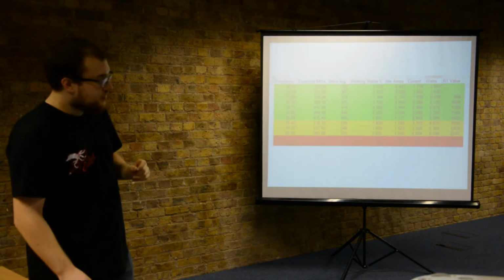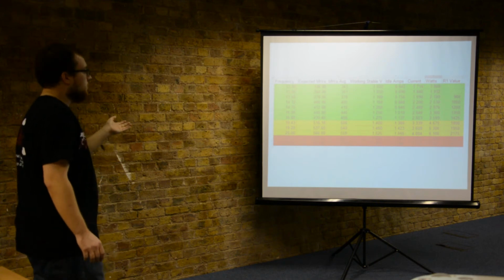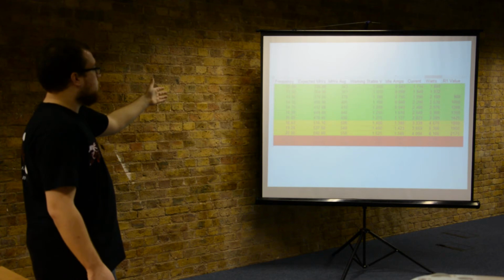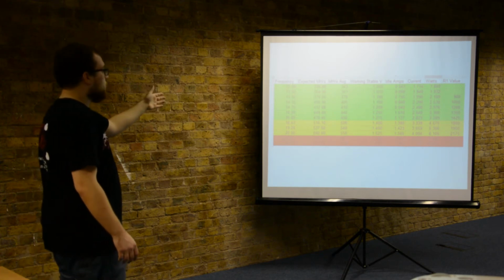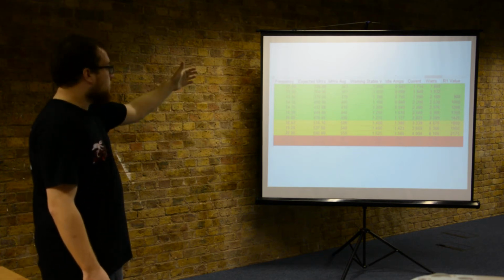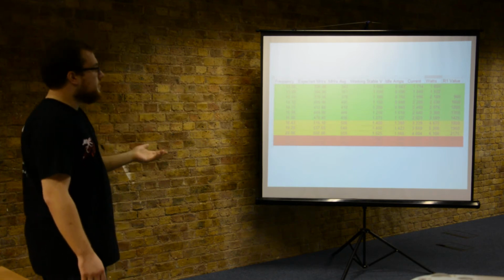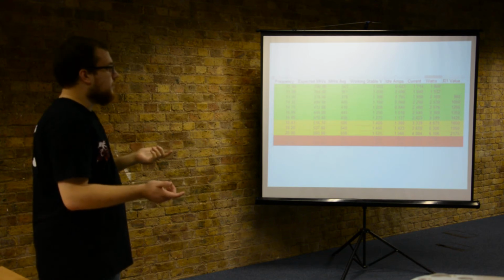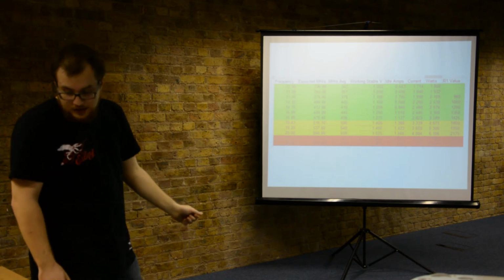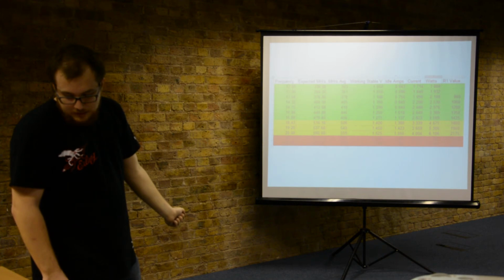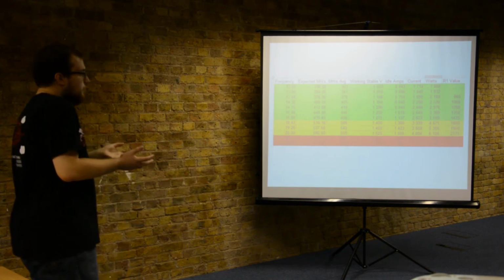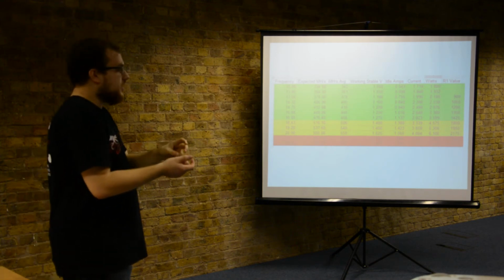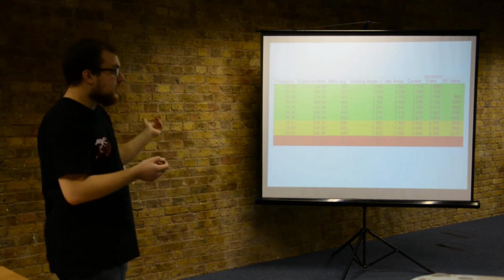And someone actually went through a lot of experimentation and provides you with this table. This is the clock frequency, or the crystal frequency, that you introduce to your system, the stable voltage that's required by the ASIC, and the value of the R1 resistor that you need to hack, basically. So changing those two parts is an easy task, really. You can just desolder the oscillator and then change the resistor.